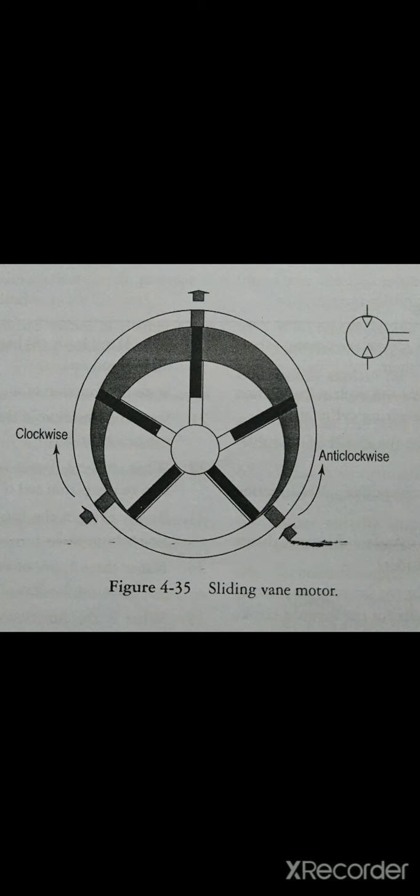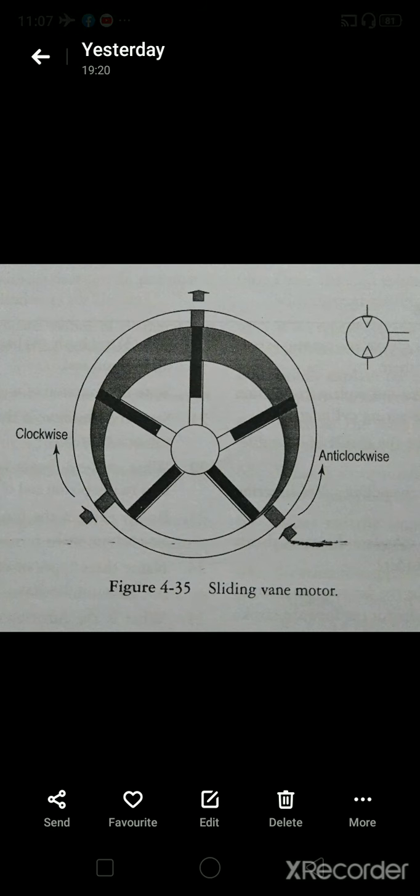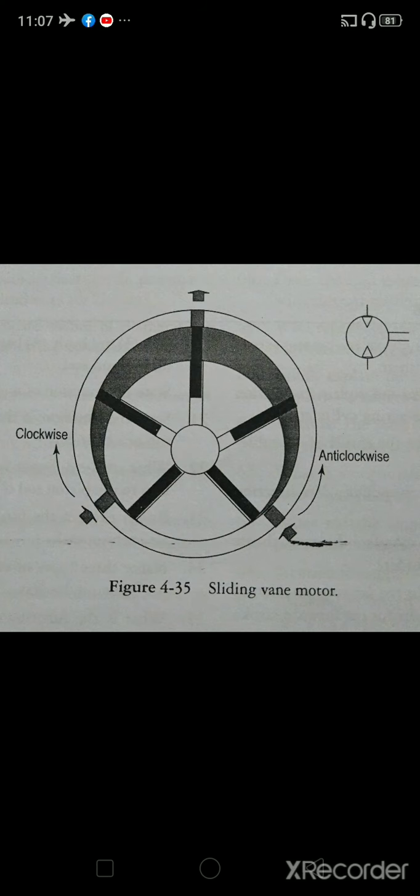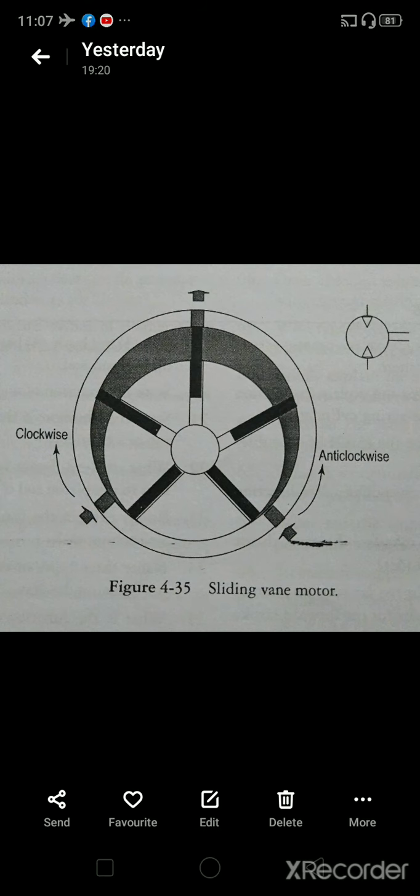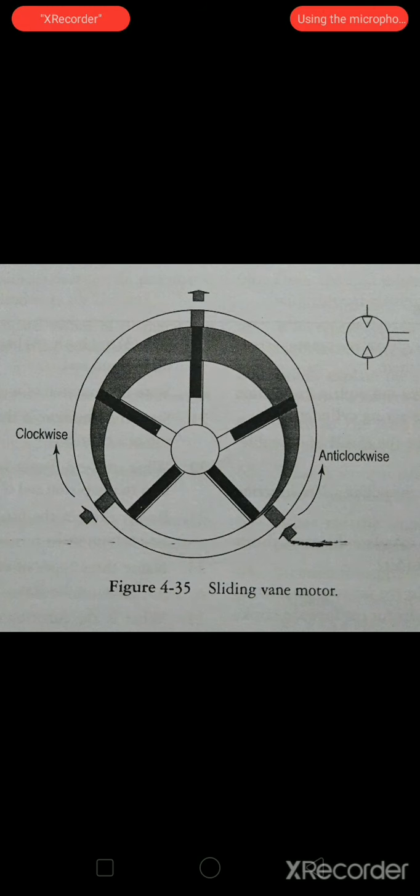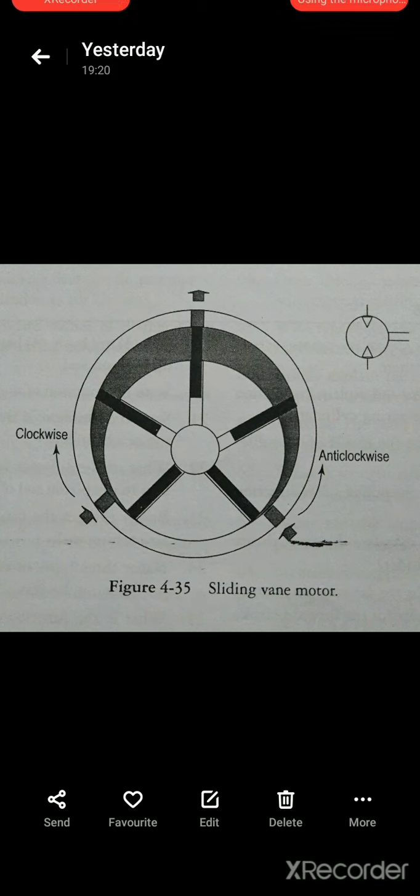They are classified as piston motor, radial piston motor, axial piston motor, gear motor, turbine motor, and vane motor. So piston type motors gain their full speed within a millisecond. It is the advantage of the piston motor. Whereas radial piston motors are available with a good power rating, from 1/8 to 25 HP you can get.